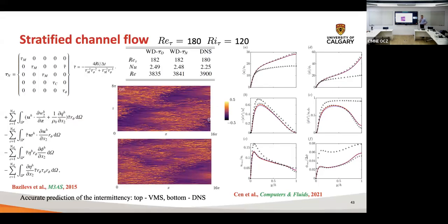Now, an interesting feature about this flow is that it has a strong intermittency. What is the intermittency? It is that you have a turbulent flow, and then you have laminar patches inside of that flow. So now if you're using classical turbulence modeling, what do you use? Are you using the turbulence model, laminar flow, or transition, or a specifically designed intermittency model? In our case, no tuning, no switching of the parameters. So literally all the cases I'm showing today use exactly the same set of constants, independently of whether it's finite elements or NURBS. So no tuning involved.